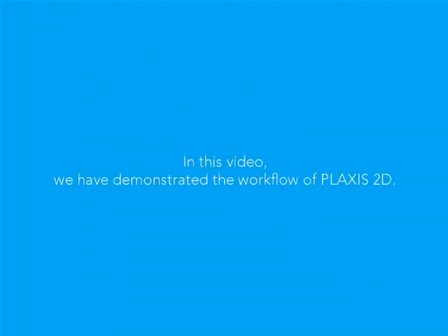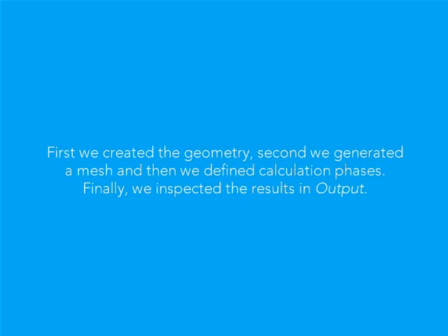In this video, we have demonstrated the workflow of Plaxis 2D. First, we created the geometry. Second, we generated a mesh, and then we defined calculation phases. Finally, we inspected the results in Output.